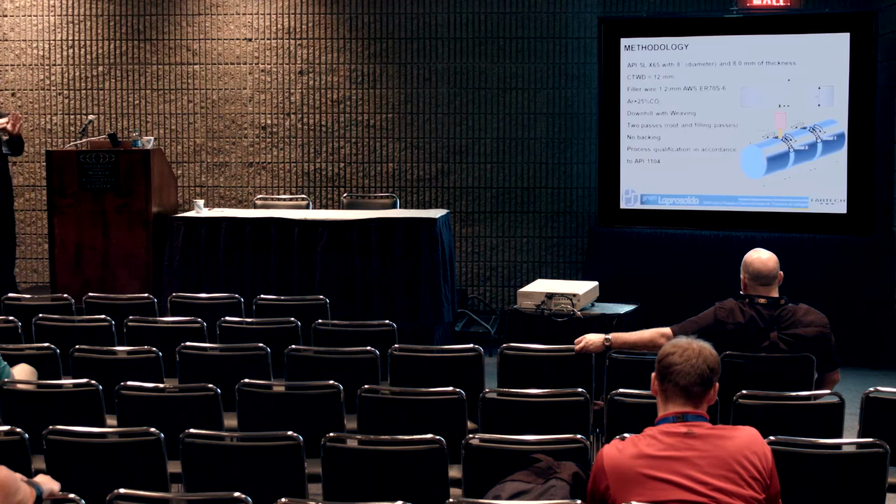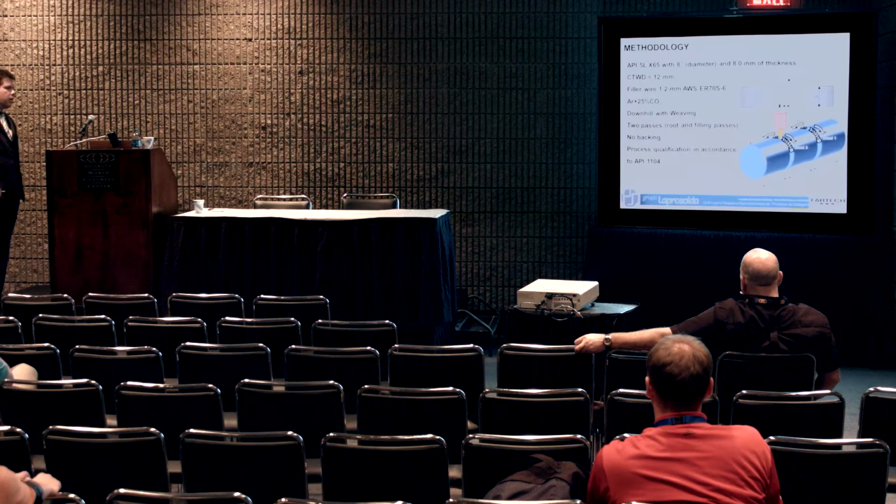Here I'm just showing the final set of parameters. For that thickness, 8 millimeters, we just use 2 passes. You don't need more than that. No backing, that's important. And we tried to qualify in accordance to API 1104.